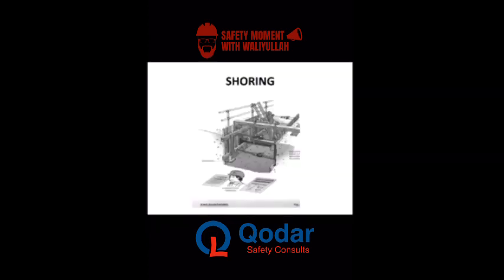This is a typical example of what a shoring experience looks like. This is being done by using bamboo, sticks, or timber. Some organizations tend to use metal, which is more expensive. But whichever method or approach the organization chooses to use, what really matters is that it should be firm and it should be approved by a competent person.